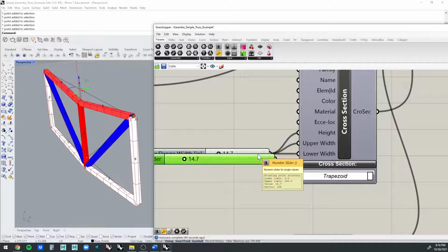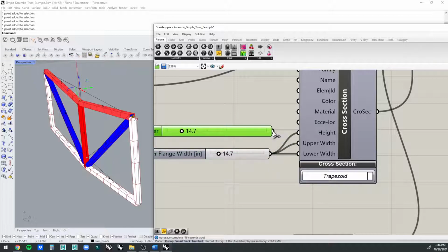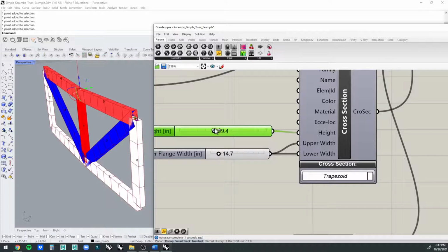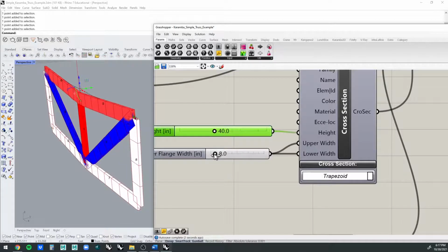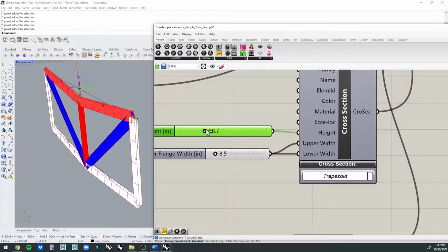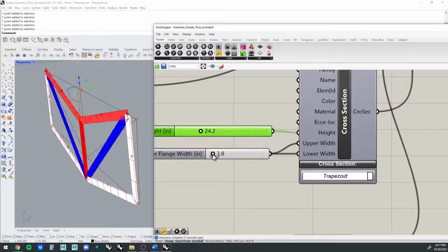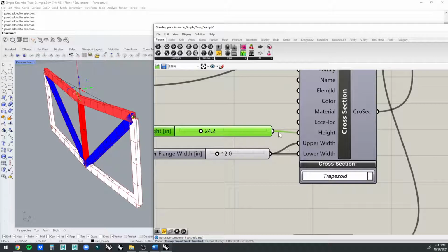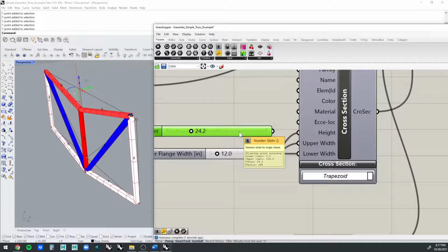But I could make a, let's say, a rectangular profile by changing the height here. So now I'm getting a taller height, but a skinnier width, for example, right? So I'm getting this irregular profile. So trapezoid is good. It gives you quite a lot of flexibility to get rectangular shapes. Let's go ahead and I'm just going to plug this back into all of them.